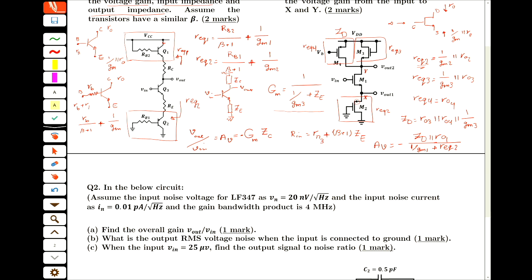If we consider RO, then the whole thing is considered. Yes, you are right, because RO has an effect in the big GM as well. So we assume that RO1 is infinity, because if RO1 is not infinity, then the big GM is changing as well.